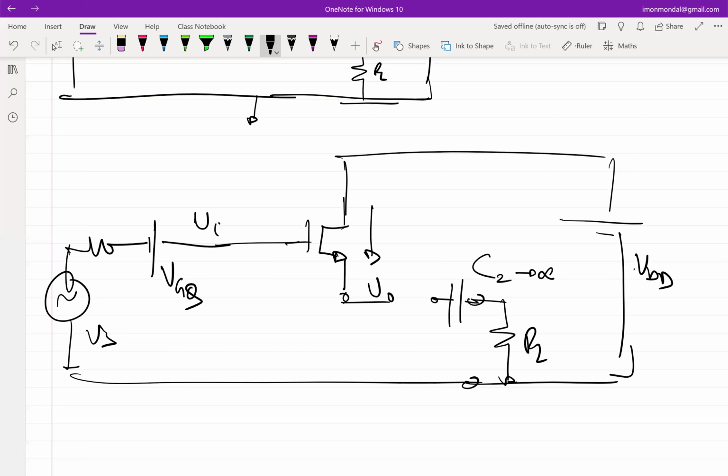Yeah, right. So we can connect a resistor here. This is definitely a good strategy. Let me call this R, maybe R naught, and connect this. This R naught, which is in our control, can sit inside the chip or inside your box and help in setting up the biases, right? And this RL can help us.